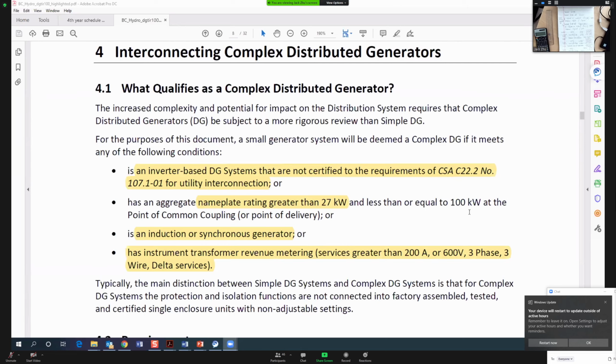If you go over 100 kilowatts, you will be considered a utility supply company. So they don't want you to connect anything more than 100 kilowatts into the system. If you have a big system and you are selling power to them, you have to talk to them individually. This guide does not apply.